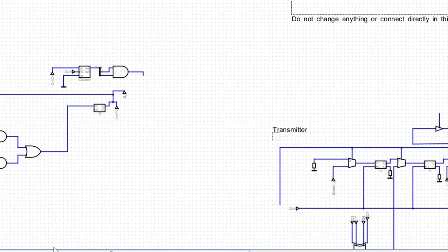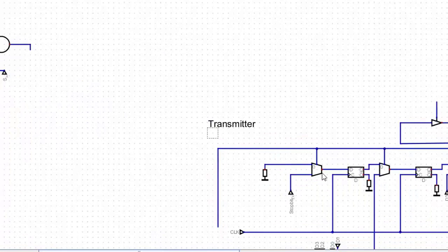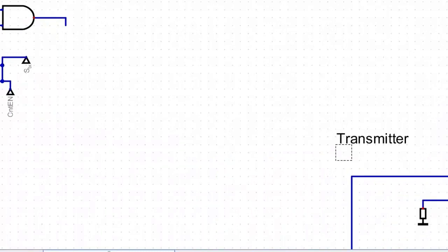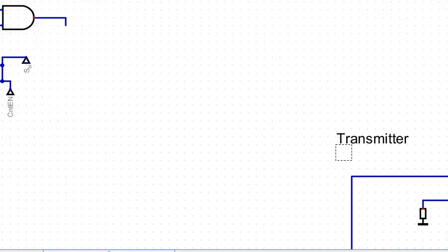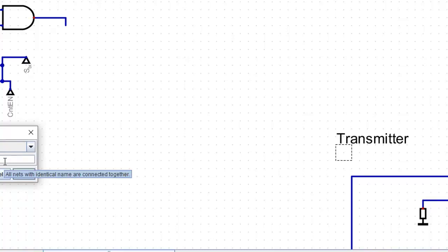Same as you have there, maybe just zoom in a bit. Just click on count enable. For this, go to the output of the flip-flop. You need to add another line called shift enable and another line called tri-state enable or something like that. You know you've got count enable there. You also need a similar thing connected to exactly the same line that you call tri-state output enable, and another thing that you call shift enable or shift not load. When it's in the state, it's either shifting or it's loading. So you need to just add that and then you should be done.